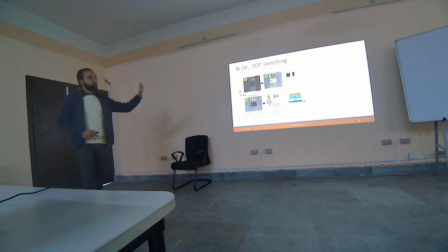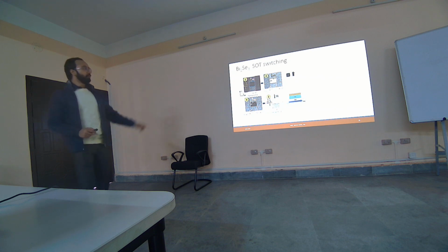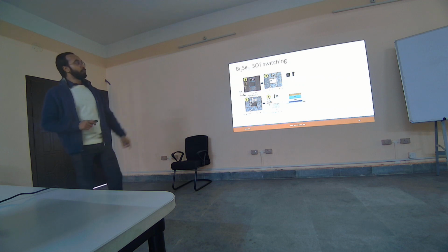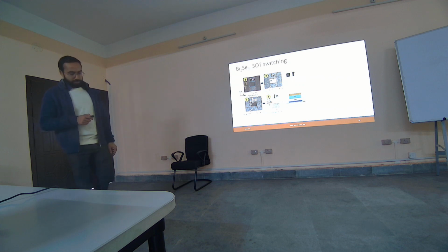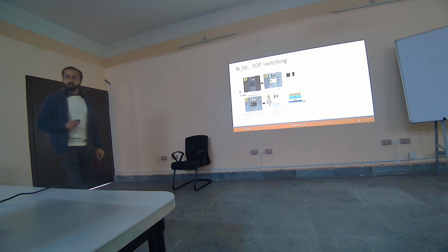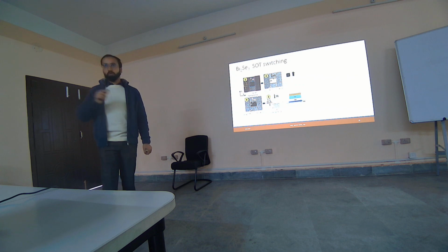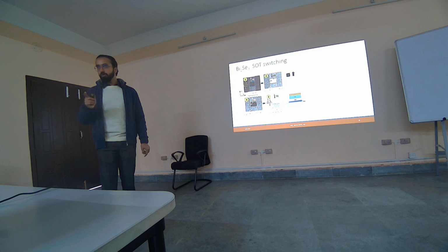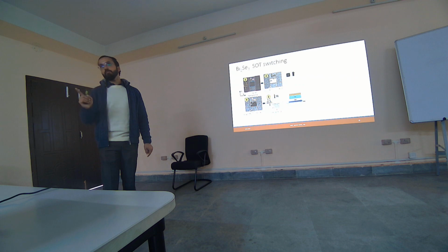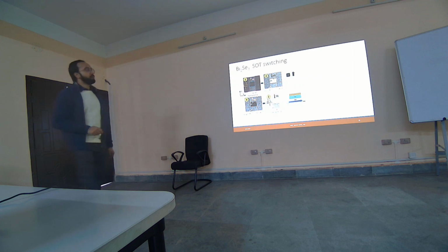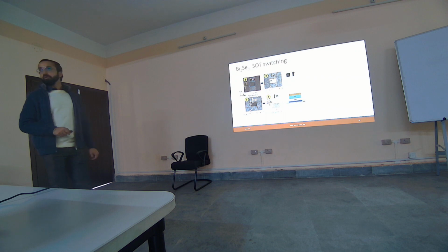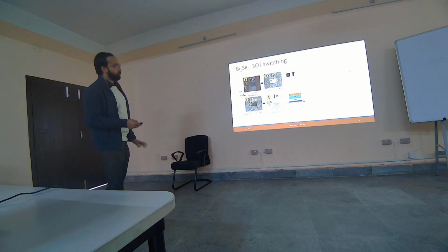So this is again another method to measure magnetic state. Here we were successfully able to demonstrate how bismuth selenide, this topological material, can be used for SOT, spin orbit torque. Why is it important? I told you bismuth selenide is insulating in the bulk, conducting on the surface, and has spin momentum locking. Therefore, at very low current densities, we are able to switch the magnetization. So that's why this work was very good for us.